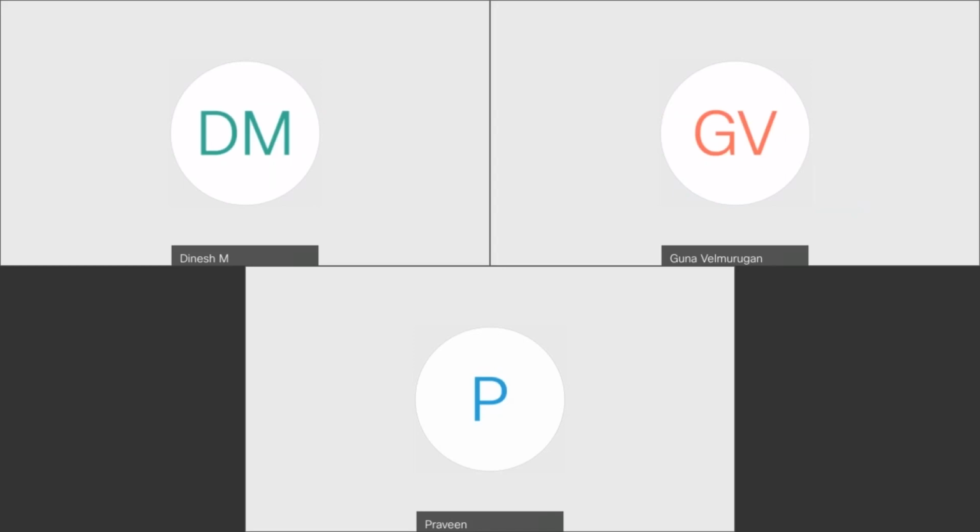They'll ask you, can you explain the procedure of investment casting? Then you should be able to say, sir, there is a metallic pattern, a metallic die, in that we'll inject wax, then we'll form the wax pattern, and then we'll form a tree of wax patterns. Then we'll dip it into the slurry, and then re-dip it into the slurry and dry it so that a certain shell thickness is achieved.